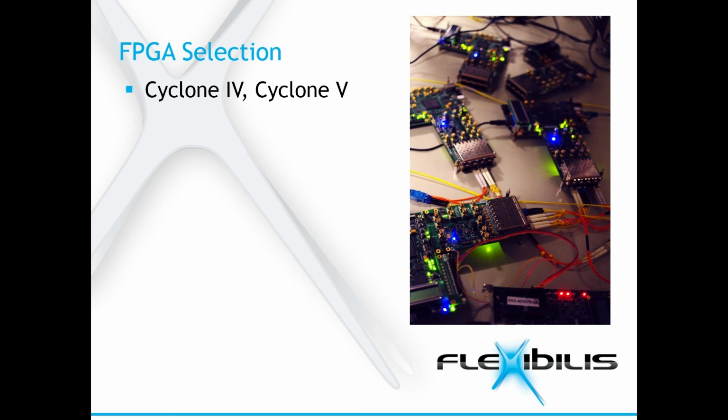If you are going to connect fiber optic transceivers directly to the FPGA, or if you are going to use SGMII to connect to your physical layer chip, you will need to select an FPGA chip that has built-in transceivers. This means you should choose GX, GT, SX, or ST family. Models without transceivers are E and SE family, and you can select them if you do not need high-speed serial interfaces.